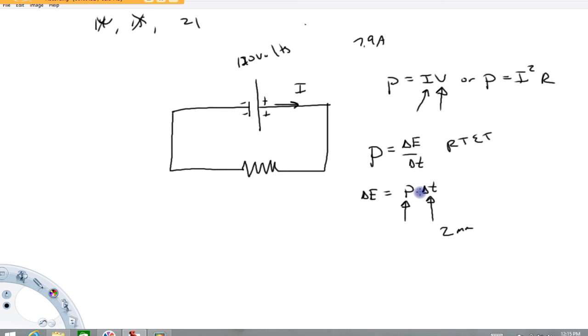Part C, where it says, what is the total resistance of the heating wire, or the element wires? There's a couple ways I think we can get at that. One is this. Remember, this is all equipotential up to that point. So red to black is 120 volt potential, and as I look here, red to black. So we can use Ohm's law, V equals IR. Put the voltage here, the current we found earlier, and use it to calculate the resistance.